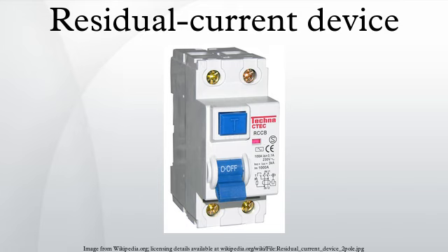Surge current resistance: the surge current refers to the peak current an RCD is designed to withstand using a test impulse of specified characteristics.